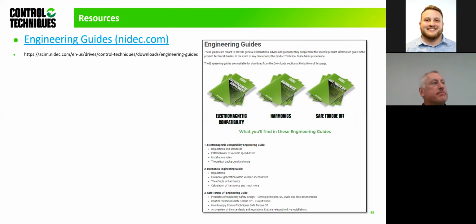It looks like I know our conversation today is focused on VFDs, but we got a question. Do you see similar harmonic issues with soft starters? Soft starters. Now, if I had to categorize a soft starter, I would put it in the DC drives area, because when it starts ramping up, when the soft starter's in, you will probably see some notching effects coming on. And the thing about a soft starter and a DC drive, it's more like a current source, and you'll probably see more of a squarer current than we see on the voltage source.